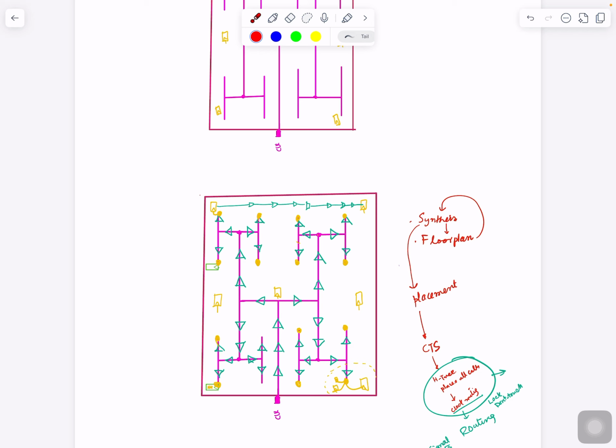Yeah, it's balanced. So you are taking the clock to the middle, then creating an edge to go there, but your flops are here, then you're creating an edge. So all the flops in these regions need to be connected to this. All the flops in this region need to be connected to this one, this one. So that's where you can cover the entire design.